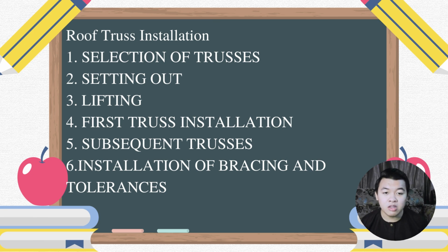The third step is lifting. Trusses must always be lifted in a manner that minimizes lateral bending stress. It is preferable that they be kept strapped in bundles until they are erected, as this reduces the chance of damage. Trusses may be lifted either by crane or manually. The choice will depend on the truss weight and wall height.